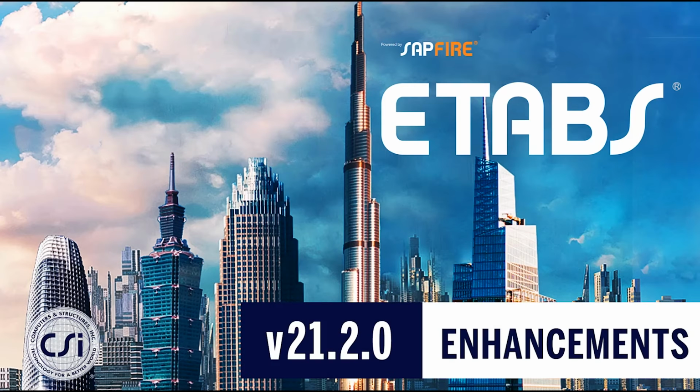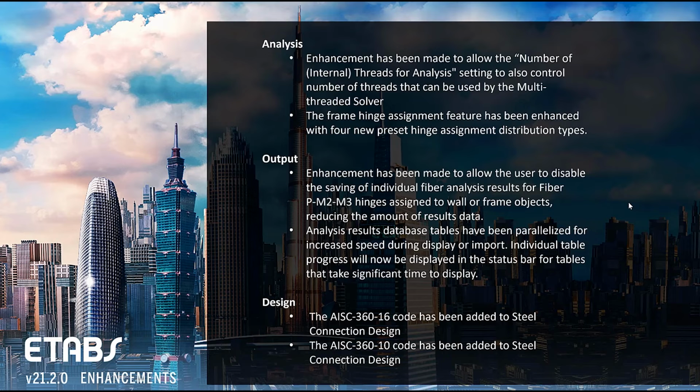In this video, we will discuss the new enhancements in ETABS 21.2.0. Here are the new enhancements. For analysis, enhancements have been made to allow the number of internal threads for analysis, allowing the user to control the number of threads that can be used by the multi-threaded solver, as well as frame hinge assignment features have been enhanced with 4 new preset hinge assignments, and we'll go over each one of these.